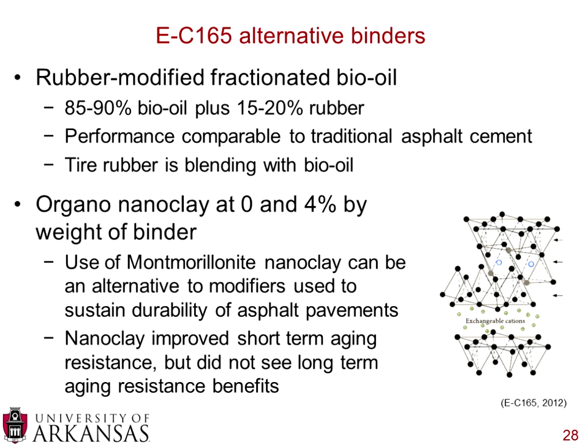And they were also quick to point out that the tire rubber is blending with the bio-oil. So a potential concern is because you may be using slightly lower temperatures, or the temperatures of mixing may be different, you may not have the blending with the rubber and the bio-oil that you enjoy with the rubber and the traditional asphalt cement. But they were finding that they were able to blend the rubber in with the bio-oil.